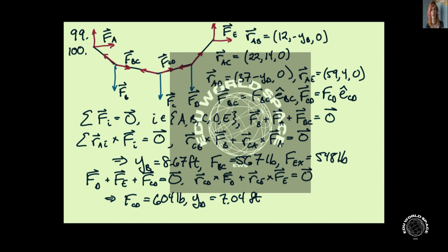That is because if YB is smaller, basically I think we're pulling this down farther, so this becomes straighter here. So that would move this point up. So again, we're adding more weight here so that it straightens this segment out, because the angle here is going to be dependent on the ratio of these two loads.